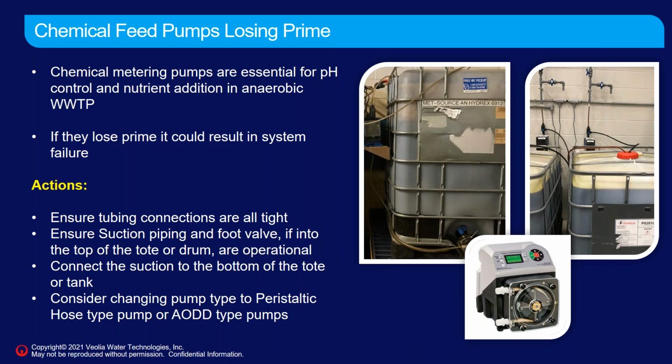Oh, this is a fun one too, chemical feed pumps. I don't know if you have a lot of these type, Pulsafeeders, or Milton Roy's or Prominent pumps. We've been doing a lot of those type of pumps in the past. And these little chemical pumps are really essential for pH control and nutrient addition. But they can be difficult to maintain prime, maybe based on how it's installed, too much suction lift, too much piping, tubing leaks, whatever it may be. So this is something you guys got to pay attention to.